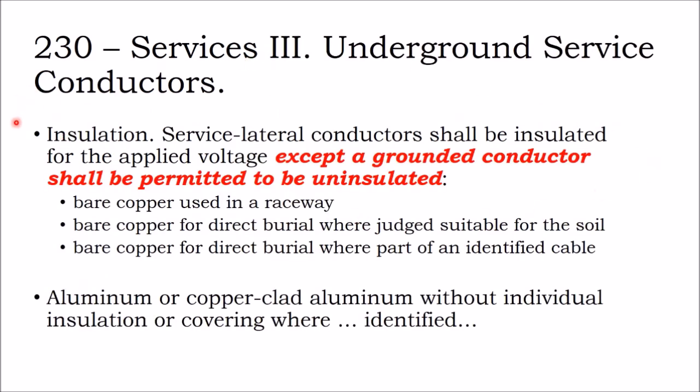Feeders, services, branch circuits, they have similar protective requirements. So insulation: service lateral conductors shall be insulated for the applied voltage, except a grounded conductor shall be permitted to be uninsulated. Now, service lateral conductors shall be insulated for the applied voltage.